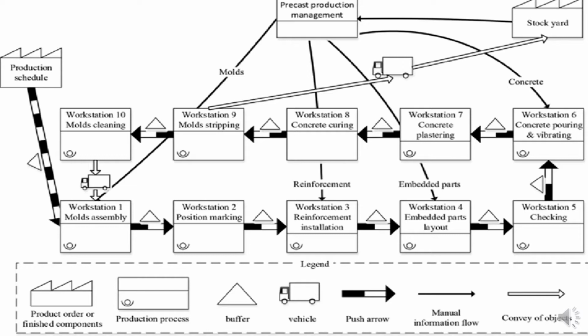Transport to site. Transport of precast concrete. The components are delivered to site in a predetermined sequence to ensure that hardened concrete is ready for instant erection. Erection at site. Erection of precast concrete. The components are erected straight from the lorry. This leads to faster erection times with reduced on-site activity.